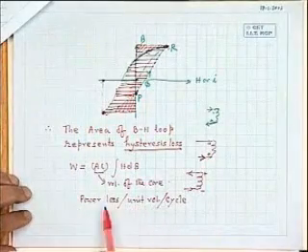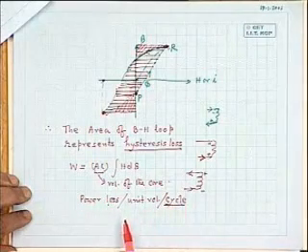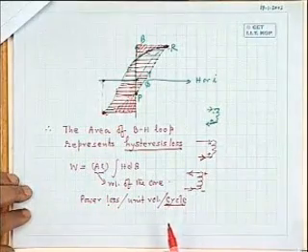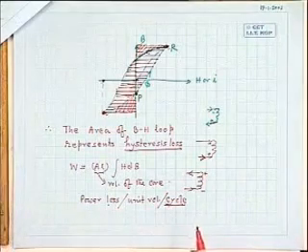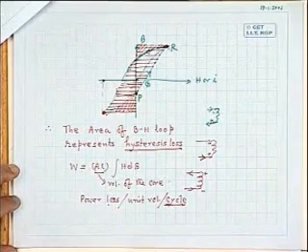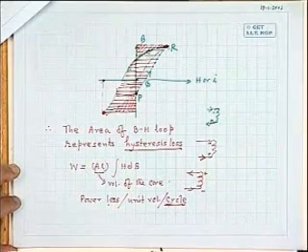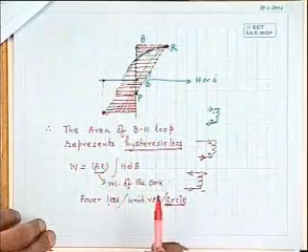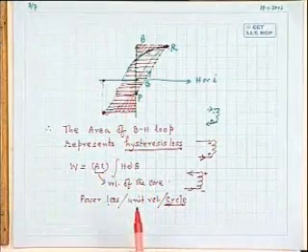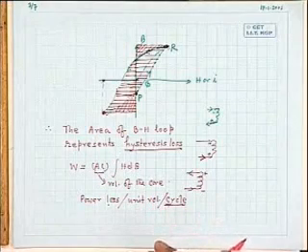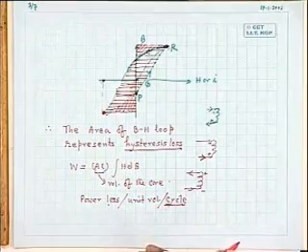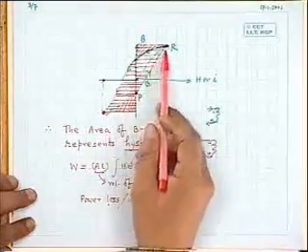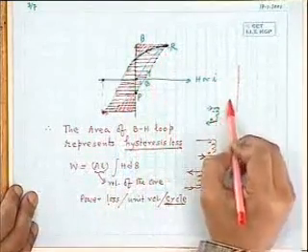Okay, so you find out the area. If you know the total volume, multiply with that. If you know the frequency of alternations of the current, that is 50 hertz in our case, we will multiply with 50 to get the power loss. I mean, total power loss I can calculate as hysteresis loss in a magnetic material. Is that clear? Now, only thing is, you have to know the characteristics of the material before you do that. And your intention will be to make hysteresis loss as small as possible. Therefore, while constructing any electrical machines involving magnetic material, you must see that this area is very small.